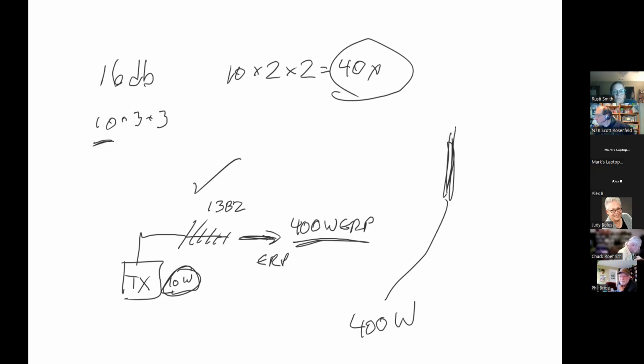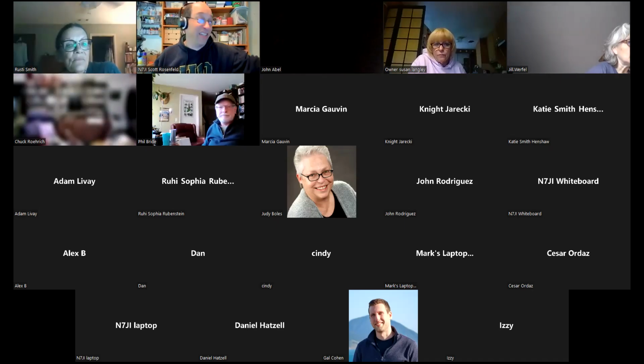You know what? I've done that. We actually did a VHF contest when I was in Maryland, and we had a kilowatt transmitter and a 13B2 antenna. And so that was 40,000 watts ERP. And it worked very well. It worked really well. We made a lot of contacts with that thing. It worked remarkably well.